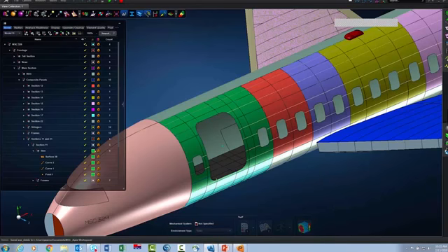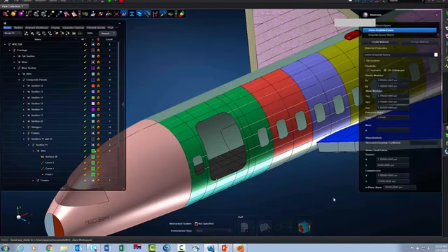So let's get started. The first thing I want to mention real quickly is that because we have added the composite capabilities, we've added 2D orthotropic materials to Apex. This is a great opportunity to have a quick script. I've got a great script I'll share with you to automatically populate your database with the materials, okay? And let's now look at defining the layup.